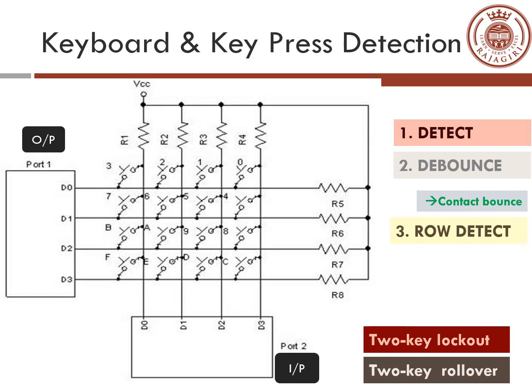The same thing happens when the switch is released. It will look as if the switch is being released twice before it settles down to a steady value. So we need some circuitry to take care of switch debounce.